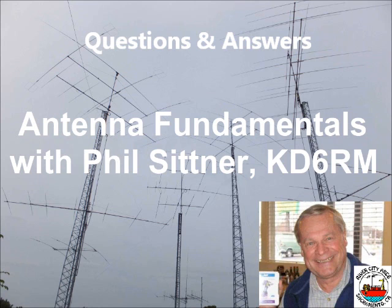Here's a new marker. See where that number 4 is there? Number 4, right here. And it's telling us that point is at 6.91 megahertz, and the SWR is 1.02 to 1. Is your antenna that good? That's pretty good, right? So that's the resonant point.